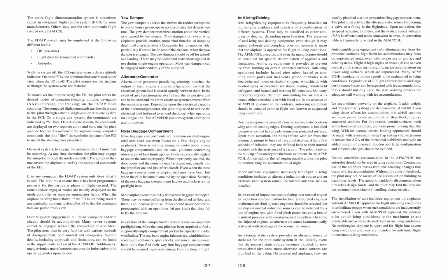Unless otherwise recommended in the AFM/POH, the autopilot should not be used in icing conditions. Continuous use of the autopilot masks trim and handling changes that occur with ice accumulation. Without this control feedback, the pilot may not be aware of ice accumulation building to hazardous levels. The autopilot suddenly disconnects when it reaches design limits, and the pilot may find the airplane has assumed unsatisfactory handling characteristics. The installation of anti-ice/de-ice equipment on airplanes without AFM/POH approval for flight into icing conditions is to facilitate escape when such conditions are inadvertently encountered.